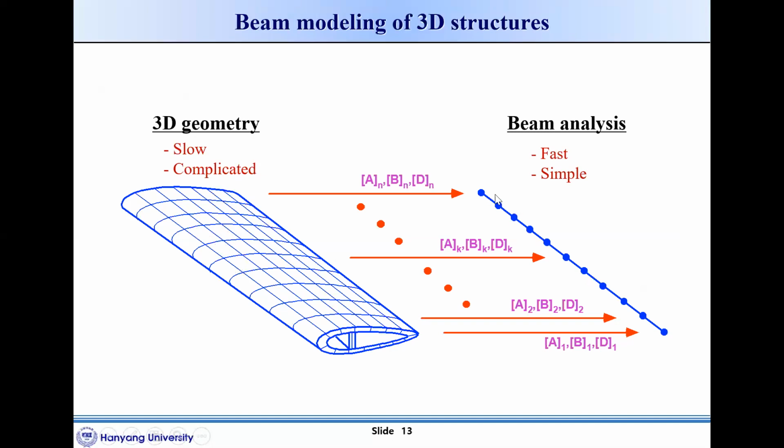So anyhow, in beam analysis, each section, we call this one the section, okay? Each section we model as one element with two nodes. In FEM, we call it a node, and one is the element. So one element with two nodes, and so on. Each element has a different section shape, and you can have any arbitrary cross sections: an airfoil, a box beam, a tube, any sector, any part along this.